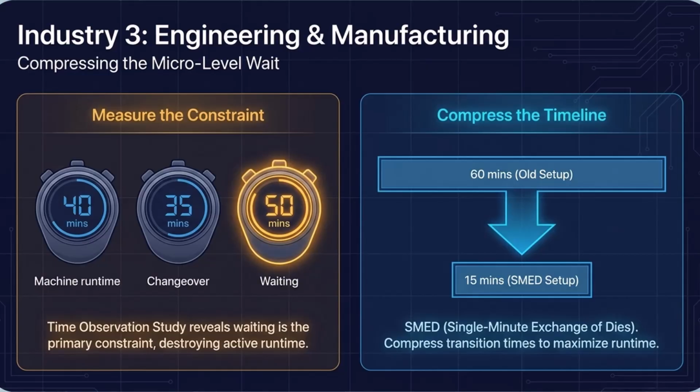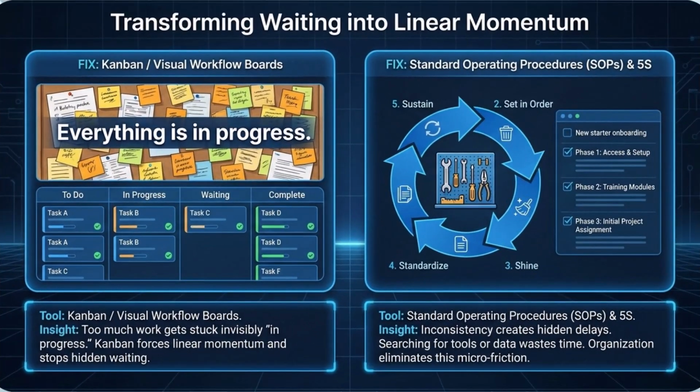Now, one of the methods we use to make sure that that's as quick as possible and the changeovers are as quick as possible is something called SMED, which is single minute exchange of dies. Now, this basically is a way that you can have a way of changing any kind of fixturing, for instance, very quickly on a machine, and it cuts out all of the wait time in between different setups of different components.